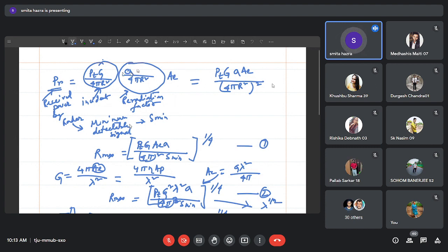So within this sigma value, the background clutter cross sections are there, plus the object cross sections, that means what I want to detect or what I want to range is also present here. So from the sigma value, we have to exclude the actual object portions, and we have to reject the other clutter.